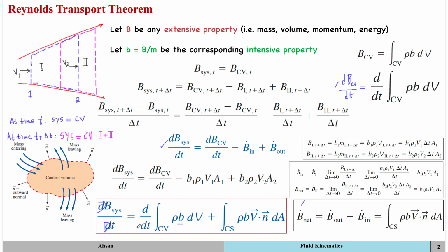What this tells you is that the Reynolds Transport Theorem and the material derivative capital D by capital Dt represent an analogy here, because the Reynolds Transport Theorem is for finite volumes, so it's giving you the integral analysis, whereas the material derivative is for small, infinitesimal volumes, so that gives you the differential analysis. But in both cases, what we're doing is transforming from a Lagrangian point of view or a system viewpoint to an Eulerian or a control volume approach.